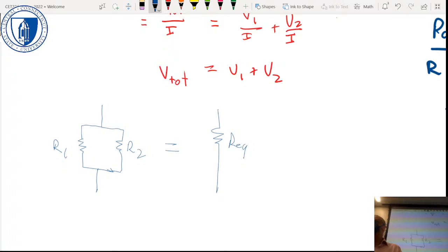Right, so the first thing we could do is something with those. What could we do with those two? Parallel circuit to make it into 1 resistor. Right, so we can convert those two into a single equivalent resistor. I'm just going to call it R45, and it's equal to 1 on R4 plus 1 on R5.